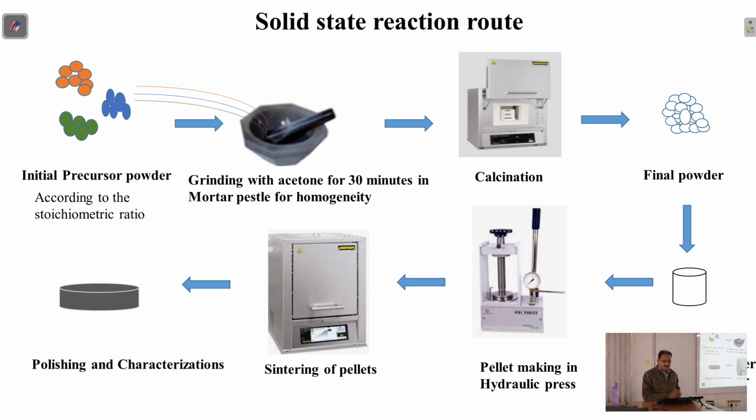To begin with, this is the usual procedure to first of all make a piezoelectric material. What we have been using generally are in the pellet form. Depending on which piezoelectric material you want to make, you have to have these precursors, right? The precursor powders in the stoichiometric ratio you first mix, then you put them for calcination at high temperature, so then the desired material powder will be made. And then generally we desire it in a pellet form.